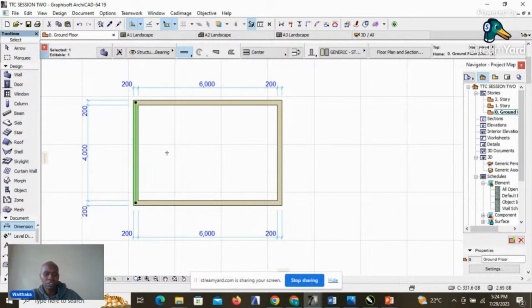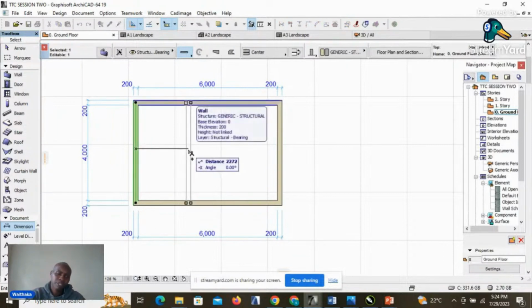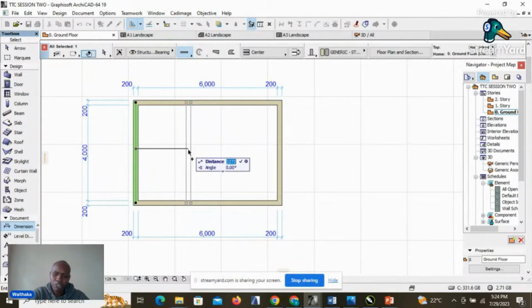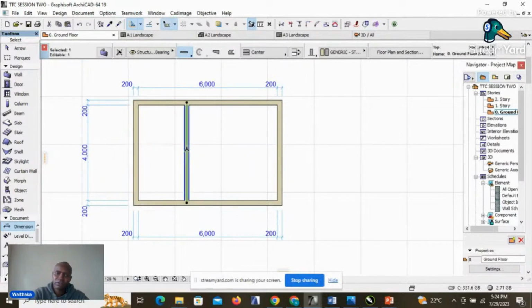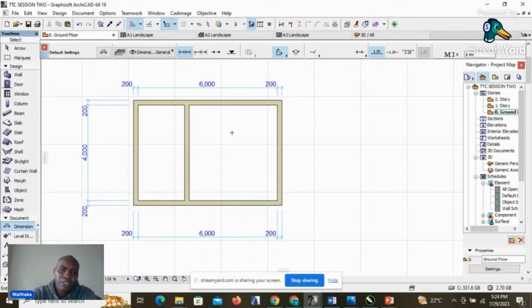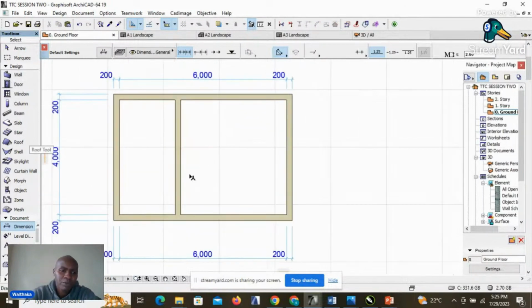So again, we said we'll do drag a copy. So we put the command Ctrl+Shift+D. We displace the wall a little bit. Then we put the command for inputting dimension, that is Shift+R, and then we put 2200 for us to displace it 2,000 millimeters apart.